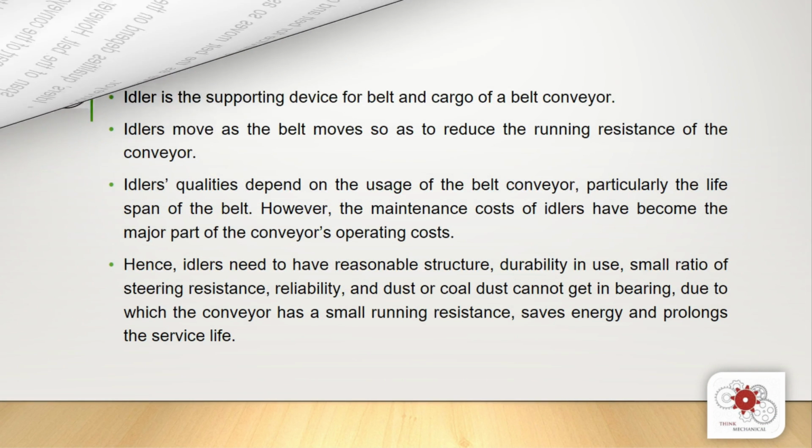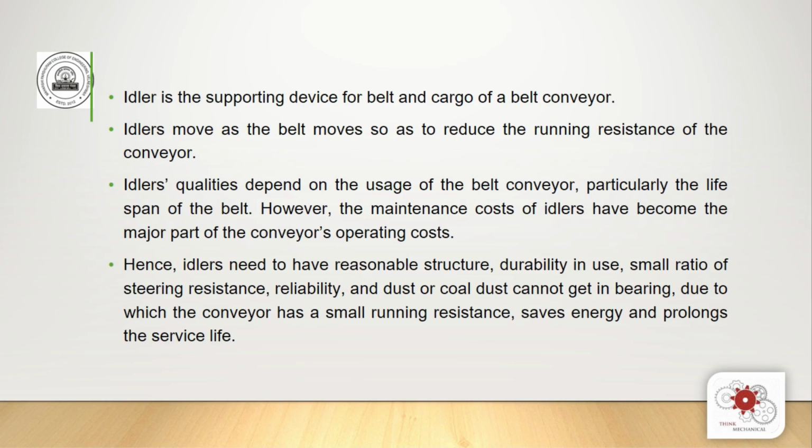Then the next major component of the belt conveyor is idler. So idler is a supporting device for belt and the cargo, which moves the belt so as to reduce the running resistance. So for smooth operation of belt, the idler should be perfectly in a good condition to reduce the wear and tear, because belt runs above these rollers or idlers.